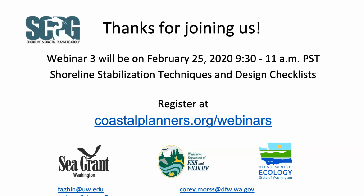And actually, I'll just grab onto this next one here too. When a small segment of beach is restored and abutting shorelines remain unarmored, what considerations need to be factored to avoid those erosional forces from adjacent armored shorelines? What's pretty common is seeing those end effects, is what I assume you're talking about. And those are described in the guidelines in Chapter 4. In the process assessment, I believe, is where they discuss that. Actually, no, it may be in Chapter 3 where I showed the table there.